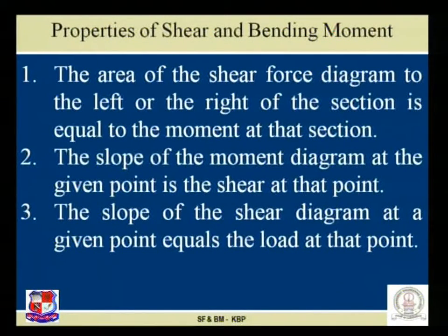Second observation, the slope of the moment diagram at a given point is the shear force at that point. Third observation, the slope of the shear diagram at a given point equals the load at that particular point or section.